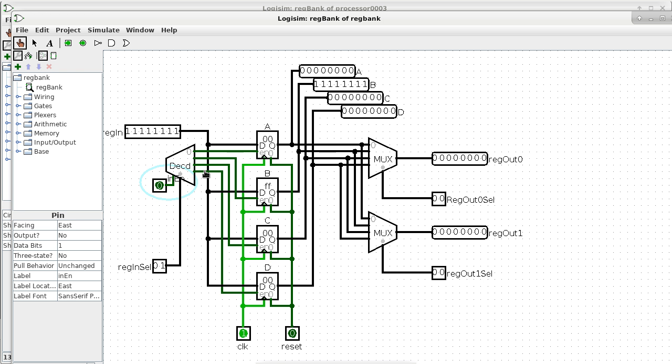Oh, you mean these? Okay, so the reason why we have those A, B, C, and D's as output pins is for logging purposes. This allows us to log the status of the processor at any time. So we'll get to that part when we get to that part. It allows you to debug your program, hopefully more easily. So they're only for debugging purposes. They don't really do anything actively. Okay. Are there any other questions about the register bank?